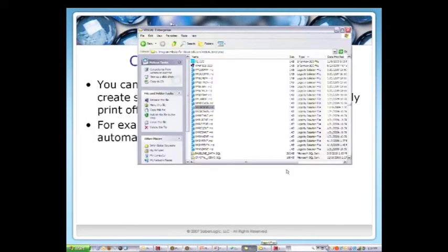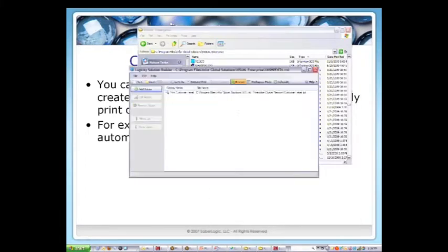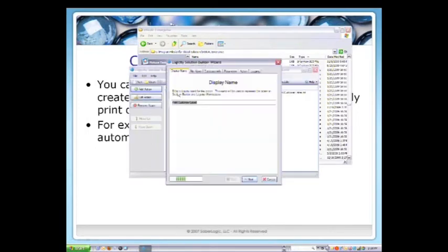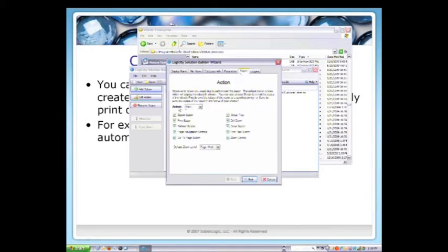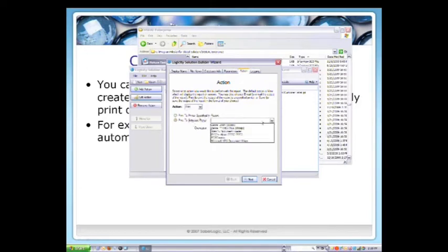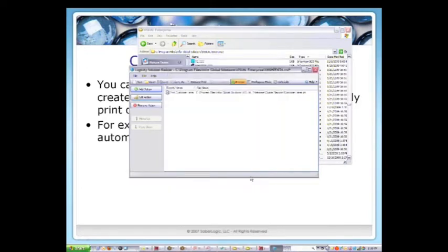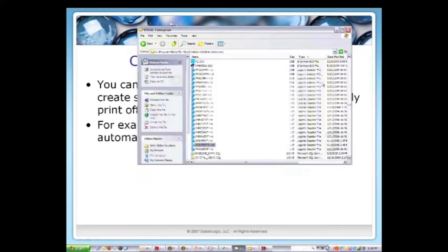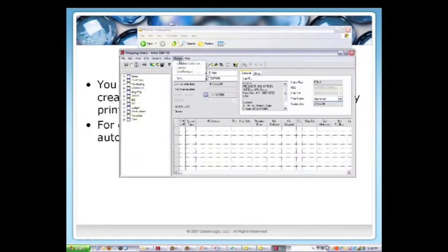But in your solution file, I've got another one here called Ship Entry A. You turn off workspace mode because you don't want it to bring up this dialog first. Next, under the Action tab, instead of viewing it, you set this to Print. You pick your printer, I'm going to send it to Z4M, and then you hook that up as an Unsaved macro.